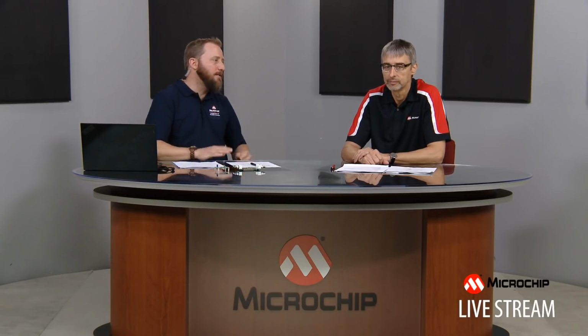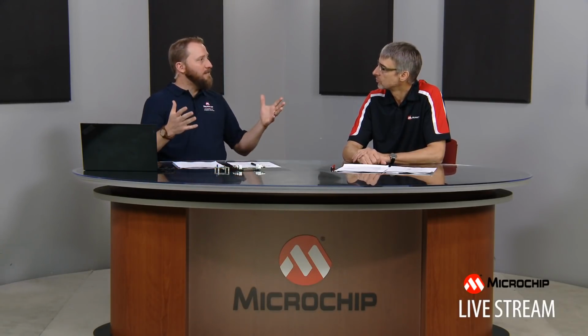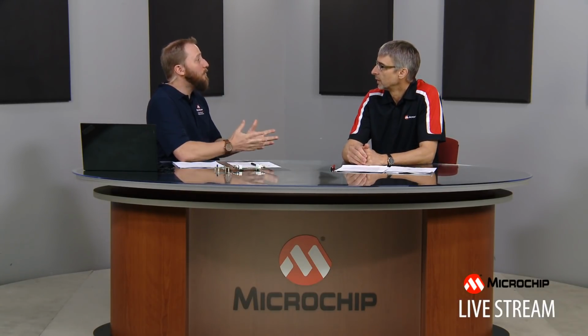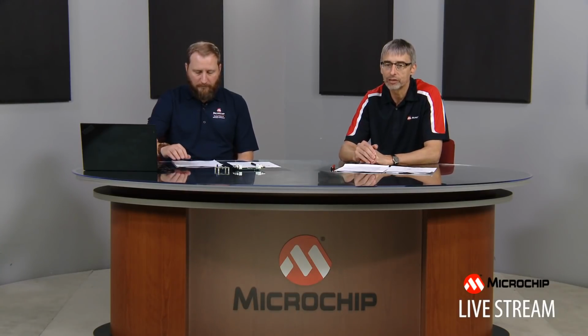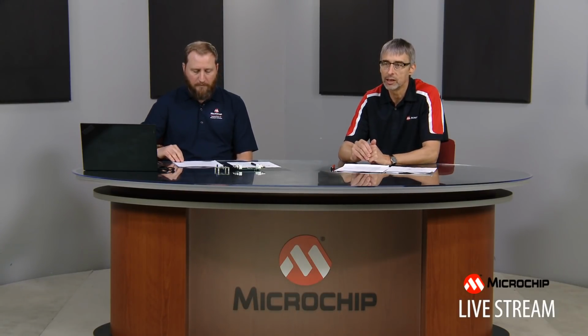So the final topic, Stefan, that I wanted to bring up, again talking about design considerations for working with these zero drift amplifiers, is time domain considerations. Yes, actually, and that's a good point, because we're getting into an area where we talk about trade-offs again. Time domain behavior, especially large signal steps and so forth, is a bit of a challenge for zero drift amplifiers. The reason for this is simply, if you recall, we have the main amplifier and we have the whole circuitry that does a correction path.